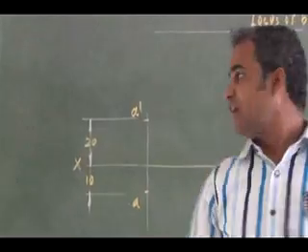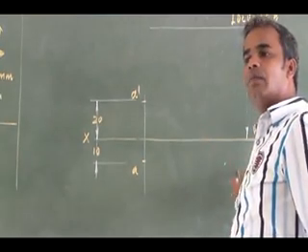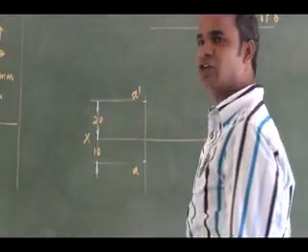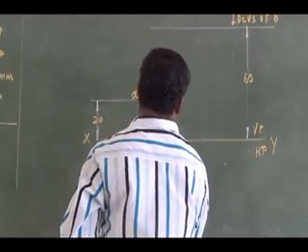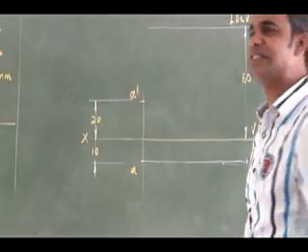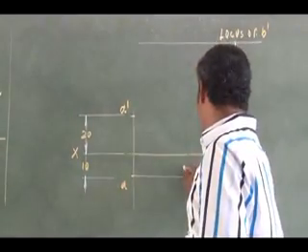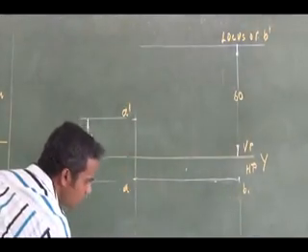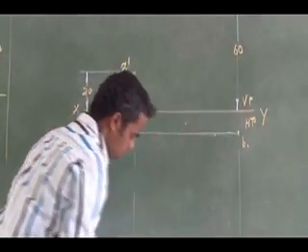Right. So then what is the data given? It is top view length 65 mm, A B1. Right. A B1 is a line parallel to the horizontal line, parallel to the reference line. So A B1, I can measure it for 65. This is my A B1. So the top view length from the first assumption, I will use the true length and the true inclination. I will end up with that top view length. This is my 65. I can dimension this.